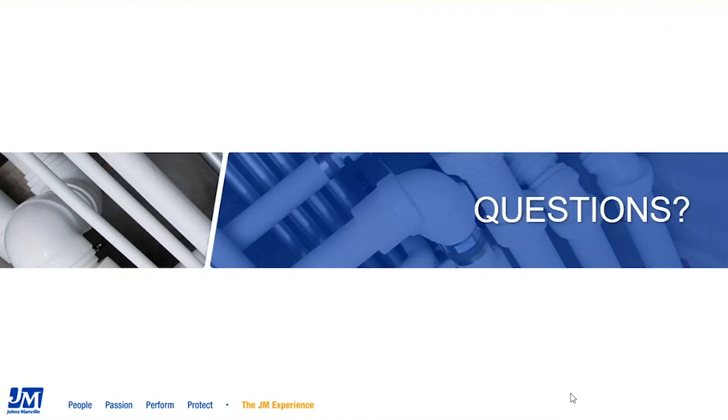The Microlite comes out of the package at an R15. The R12 is actually an installed rating, and that assumes a 25% compression. So as long as you have a compression that's less than 25%, you'll be okay as far as maintaining that R12. The only problem you'd really run into is if you overcompress the insulation, and in those circumstances, you may get less than the R12. But it's an R15 out of the package, R12 installed.